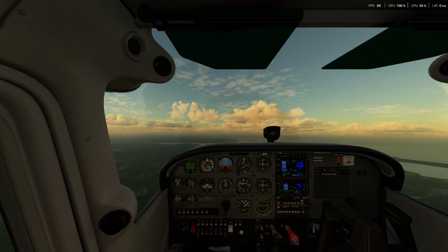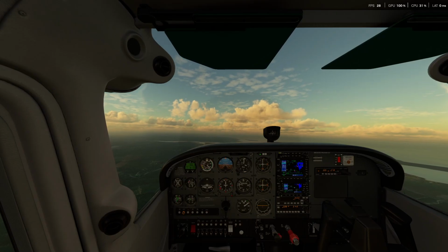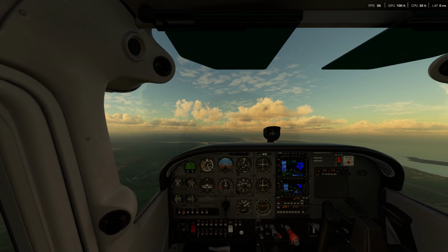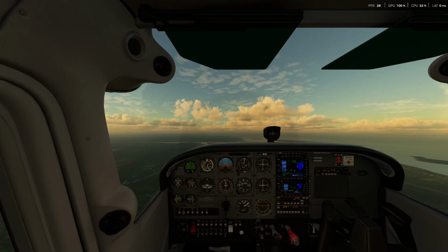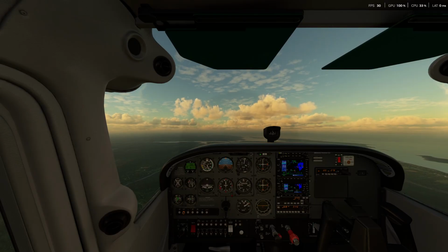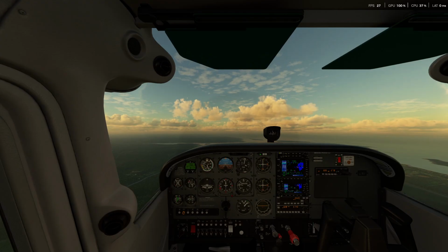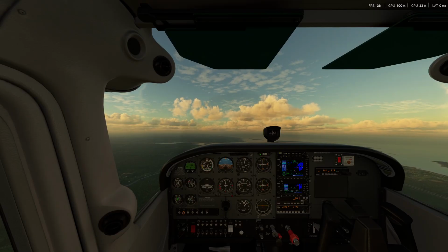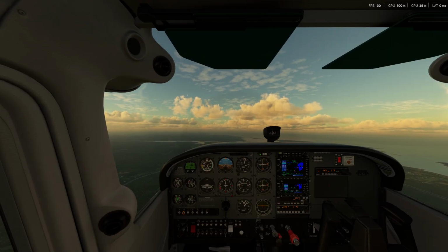We're going to go ahead and bring those down. I'm not going to adjust the trim or throttle just yet. We're going to let the speed increase. It's roughly right about here. So we'll go ahead and bring back the throttle, and trim out at 3,000 feet.